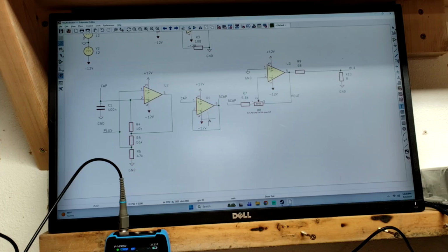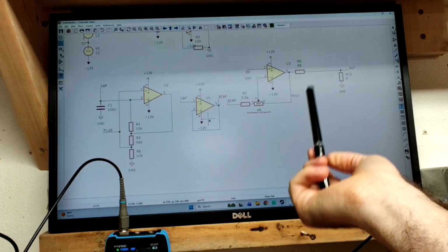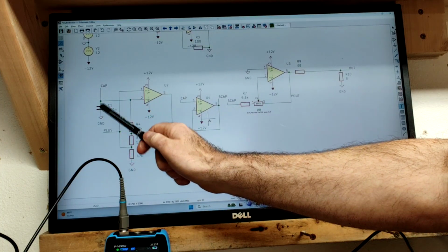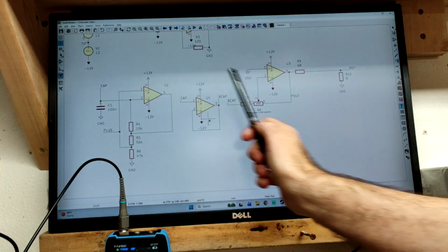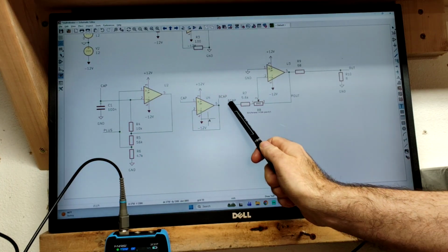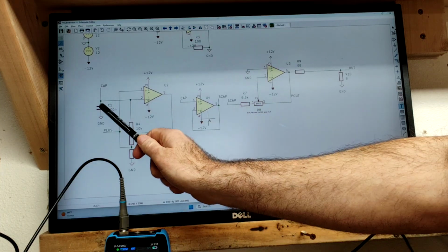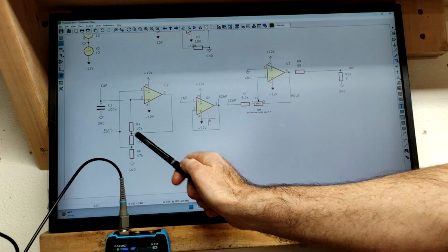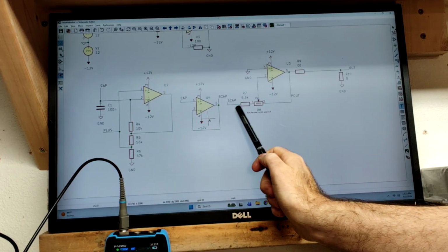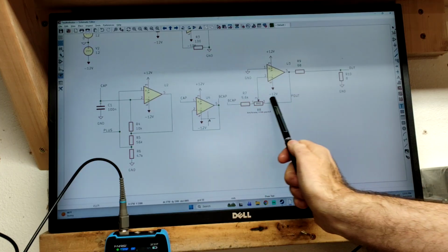Okay, back here at the schematic. This is the way I wired it up initially, and I thought it would work, but it doesn't. There's a problem. I have my capacitor here that I measure my voltage across, and the first way I wired it is I came straight from this cap to this amplifier circuit. And what happens is that this capacitor, in addition to being charged or drained through this resistor here, it also has these resistors here and this voltage source here. And so we have some additional current going this way.